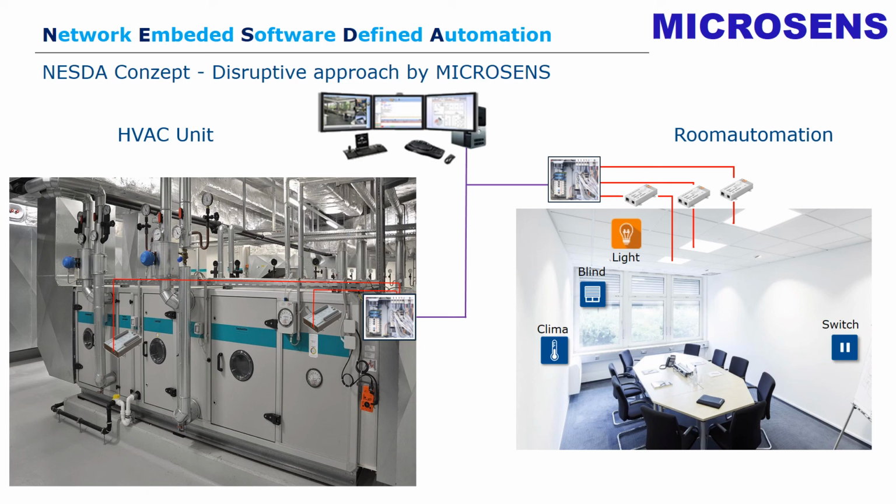We cover with the EnOcean protocol wireless switches for buttons, devices for climate control like temperature sensors in the room, or blind actuators. We are connected by cable and provide also over the micro switch, which is located here, network, and we provide also over PoE voice over IP for the phones and VLAN activity.